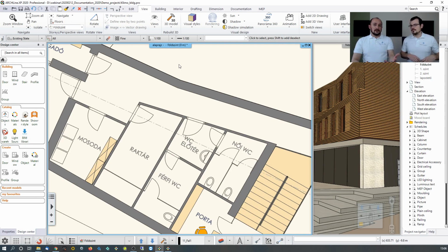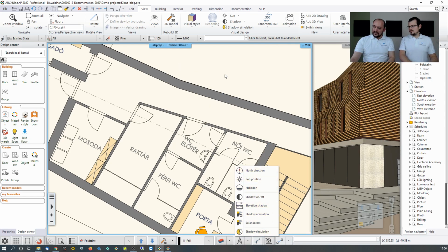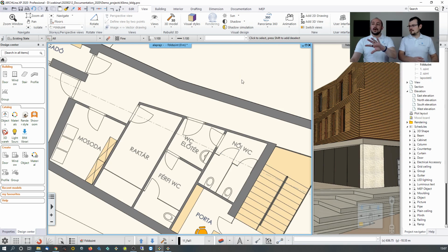And there's the real north, which can be defined with this tool here, which is the north direction, and this is something completely different. So when you rotate the drawing, when you do what I just did, you won't demolish the orientation of the building on Earth. So this is absolutely good for all sorts of editing without having to think of what has changed with the real orientation, because it won't change.